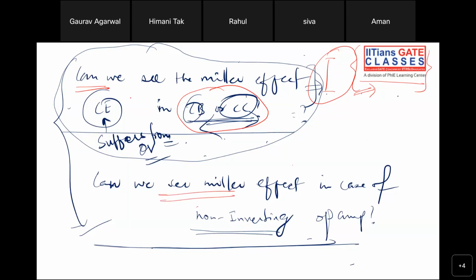But there is various information you can tell. See, in electrical engineering there are only two kinds of quantities. One is voltage, one is current. After all, you are applying those inputs to be amplified, because your input is at very low strength. So you can apply either voltage or current and it will get amplified. In the output also you can get voltage or current, right? So there are two quantities in input, two quantities in output. In this manner four kinds of amplifier you can realize, or you can also tell depending upon the input and output resistances, because each amplifier will have its own input resistance and its own output resistance.